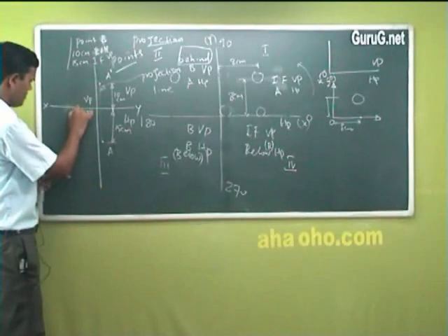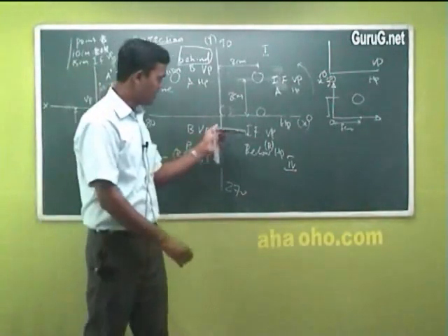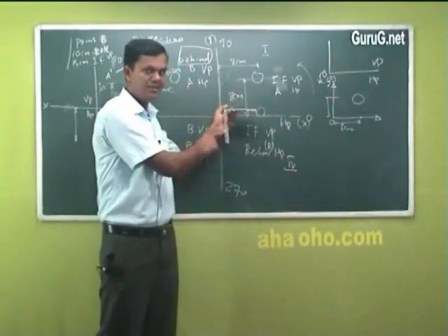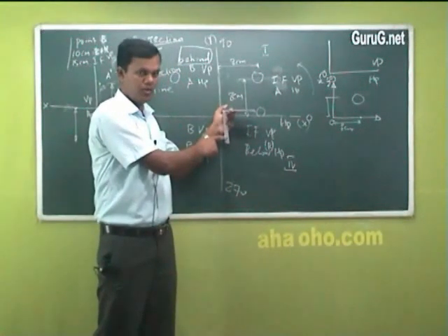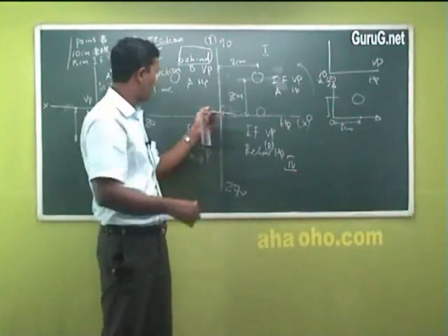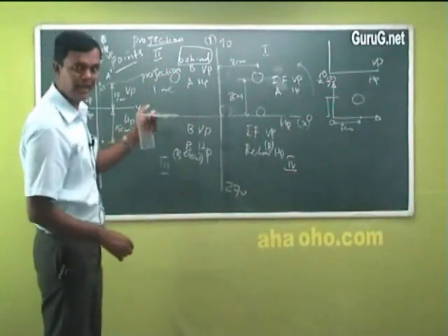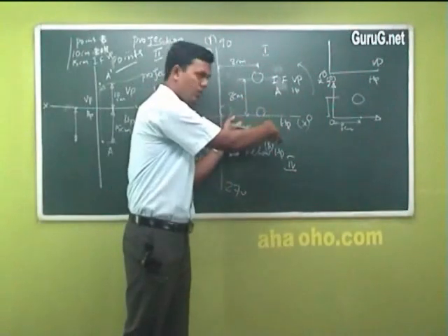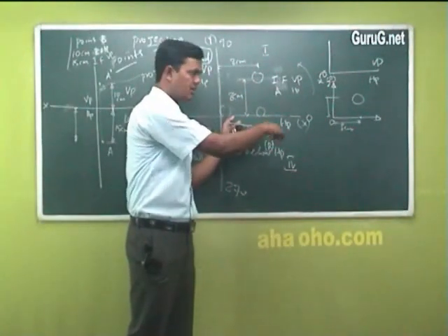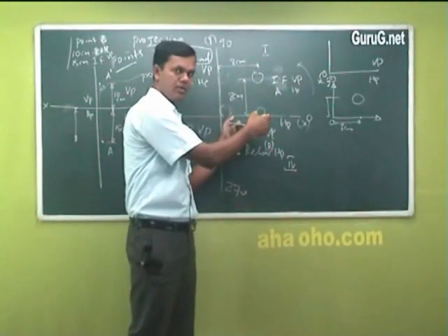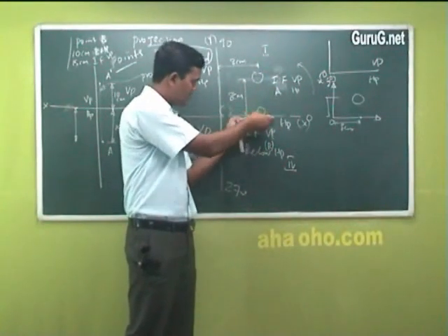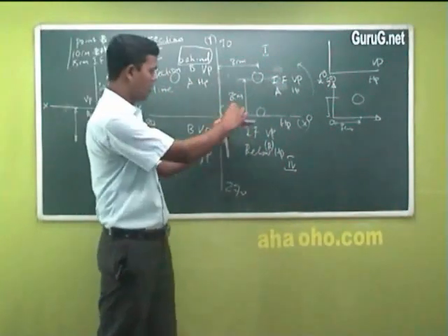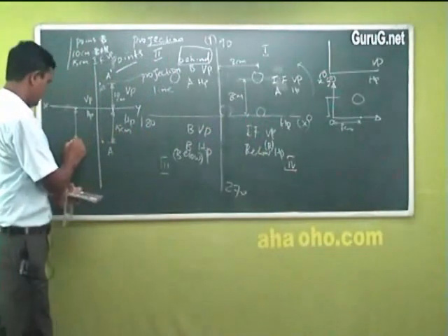Okay? Kindly remember, when you come to the fourth quadrant, HP is here and VP is here below. In front of VP is like this, and 10 centimeter below HP is again below. Where will you see this below? It is 10 centimeter below. How will you see this? Again in the front view. This place is in front of VP and below HP, so it will come here.